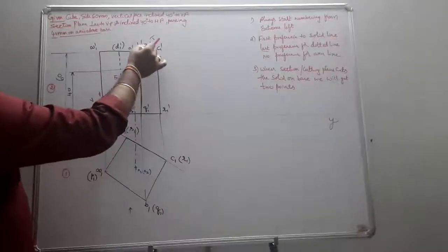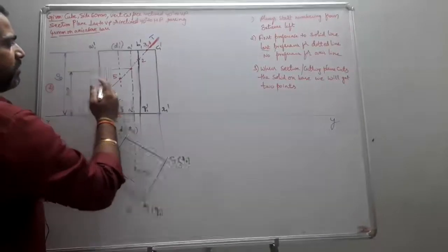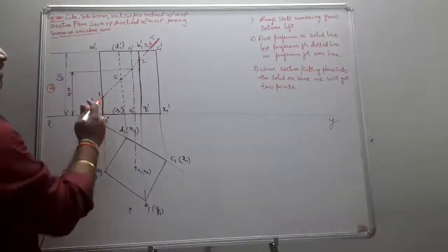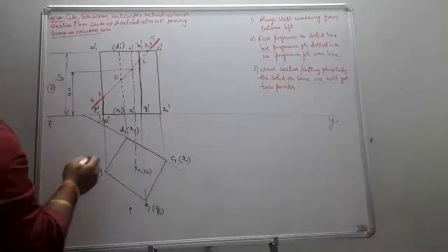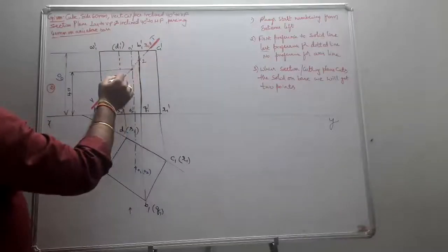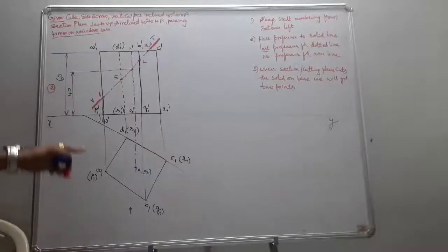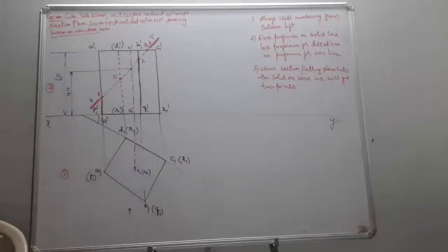Next one, I come to here. Again, I come to the reversal procedure, so starting from left to right and then from right to left. Why? Because I did not give marking points to the dotted lines yet. Once I go from left to right and it is completed, I again start from right to left. So 4, and another point on the dotted line is point 5. And I did not give any point to the axis. Why? Because there is no preference for the axis line. Students, is it clear now? Is it clear?